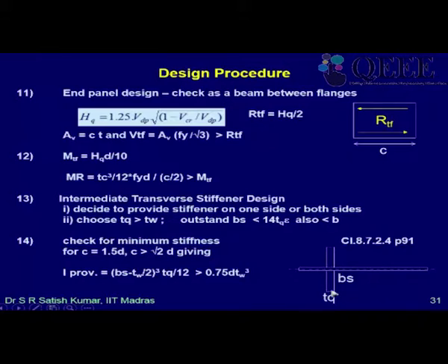So this L-shaped cross section, whatever, that has to be now checked for buckling about the weak axis, this axis, the center line of the web, and we need to make sure that it will take the load between the flanges. It will not buckle as a web buckling. Okay, so that has to be checked.